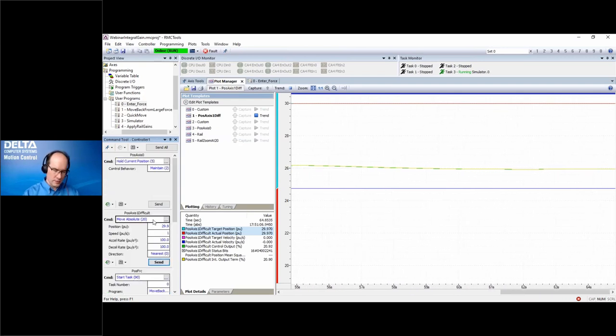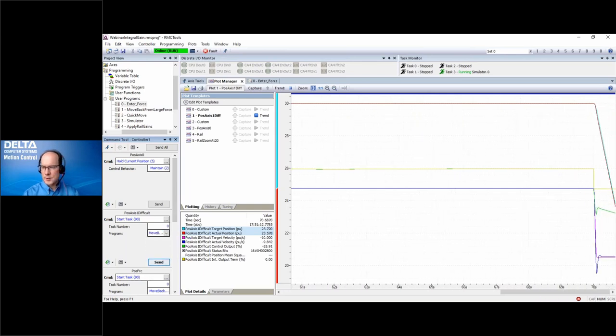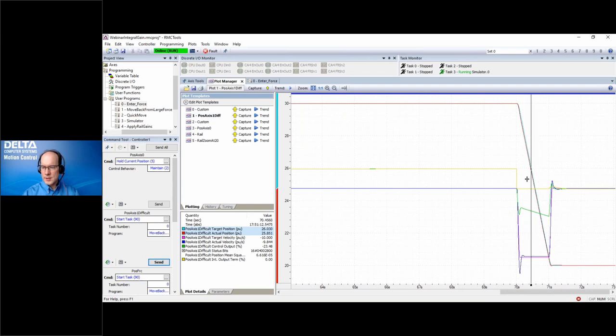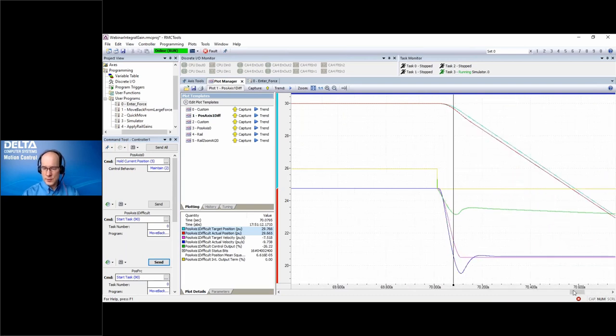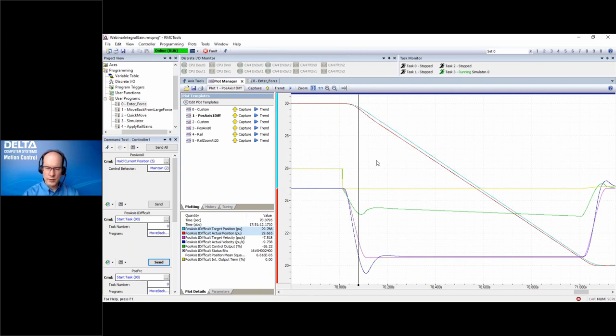And then if we move back, let's see here, move back from large force, we can see here, and this is that exact same situation as we had in the position force axis, just so we're not controlling the force also. So right here, the control output was up high. We'll turn off the integral term. We see the integral term is pretty much using most of that. And then the control output drops down because the integral term dropped down to 0. And now right away, the move can start with a negative control output and start moving right away. Now we see it's not tracking very well because it is set up to be kind of a difficult system.